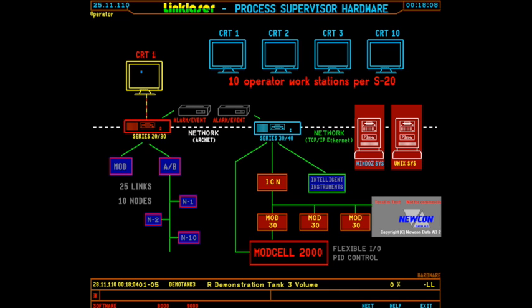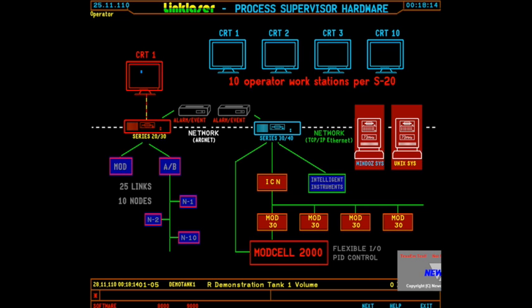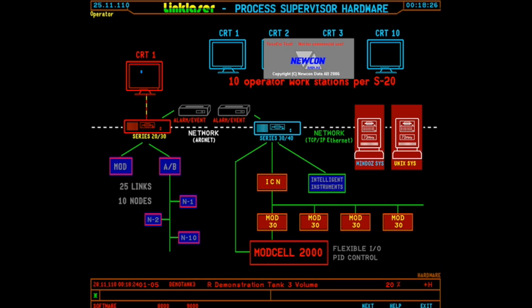These are the things in blue and purple below the flashing red and yellow hardware. And you can assign any protocol to any data acquisition link, and then you can have multiple nodes on that link. The only limitation is that one link can only have one protocol, so all of the nodes must talk the same protocol. Then of course we can network Motorola boards together.